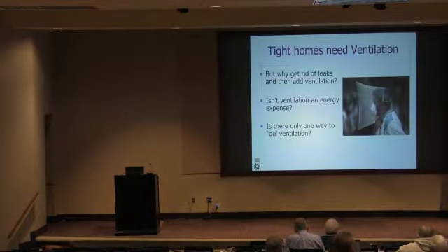Aren't there ERVs, these heat exchange systems that can clean the heat off the home? Yep. I've got some slides coming up on that in just a minute. And there are new technologies, ERVs, HRVs. In our climate, we really want an energy recovery ventilator, not just a heat recovery ventilator, because it'll do some latent as well as sensible recovery, so it'll manage moisture a little bit. And the best products that we're seeing now are dehumidification ventilators. I'll show you some of those in a second.